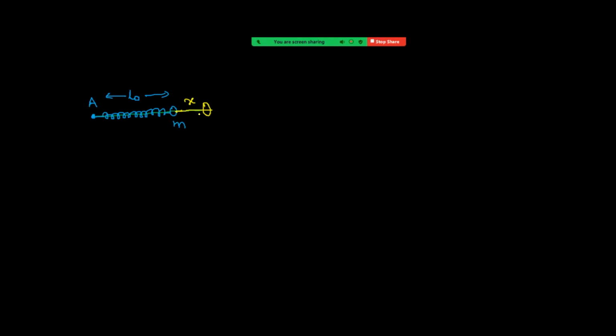This sleeve is following circular path. Now see who provides centripetal force. Because of elongation, now spring force is there, which is providing centripetal force. So centripetal force is given by spring force, that is equal to m r omega square. Radius will be L naught plus x. Okay. So we have taken force equation.